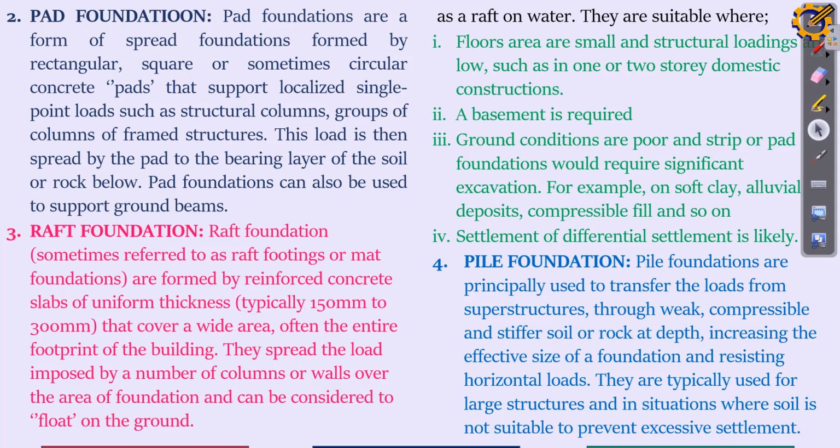Those two tall buildings behind Environmental Science are made of pile foundation. After they drive the piles into the ground, they create a beam on it, and on that beam they create a concrete slab. So that is pile foundation. They drive them in, and we have several types of creating pile foundation. We can do precast piles or cast-in-place piles.